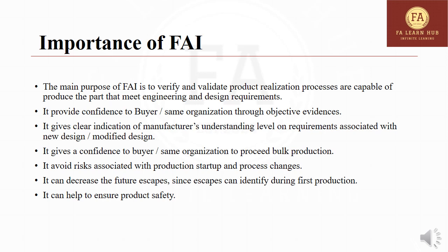Here the customer requirement is that the bareboard test shall be conducted with 250 volts in power lines and 50 volts in signal lines. The engineering team of the PCB manufacturer decided to conduct the full bareboard test with 250 volts for both power lines and signal lines, since 250 volts is the highest voltage. They conducted the bareboard test, it passed, and they dispatched it to the customer.